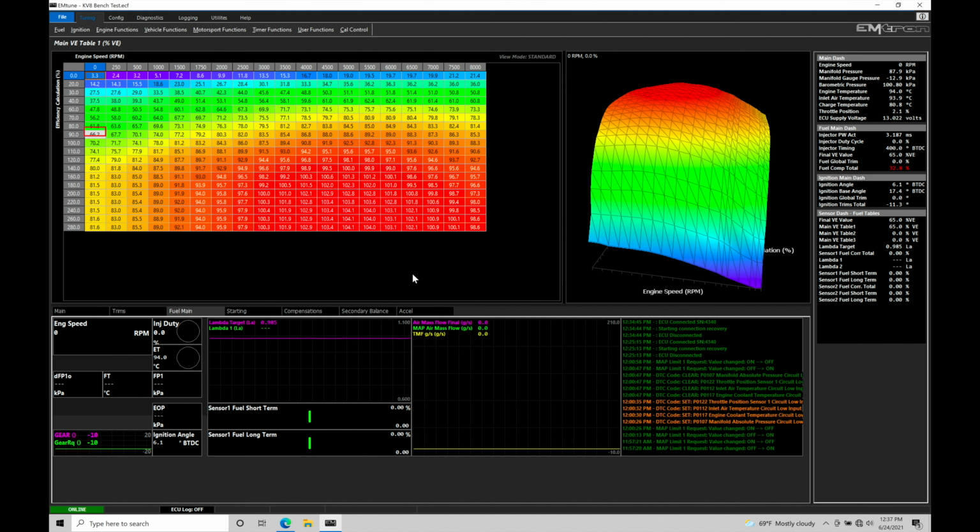The basic sensor inputs that we have to have in order to make the engine run would be map pressure sensor, intake air temperature, throttle position sensor, and engine coolant temperature. So all of those are needed as basic sensors. Anything additional above and beyond that is definitely going to improve our logging capabilities so we can see more data and information on how the engine's running. We can also take some of these particular sensors, such as a fuel pressure or a Lambda sensor, and allow that to perform advanced fuel calculations and actually feed back into the Emtron to take action and alter what the fuel delivery is going to be for the engine, for example. So there's going to be a lot of reasons why we probably want to add these additional sensors on.